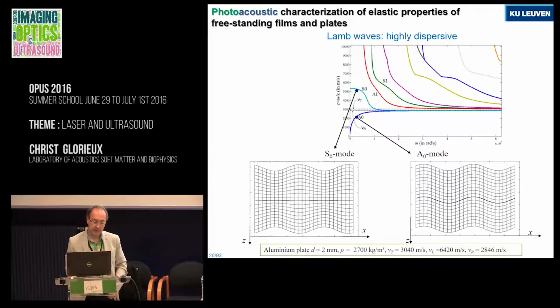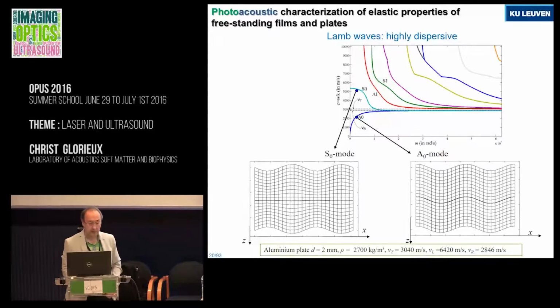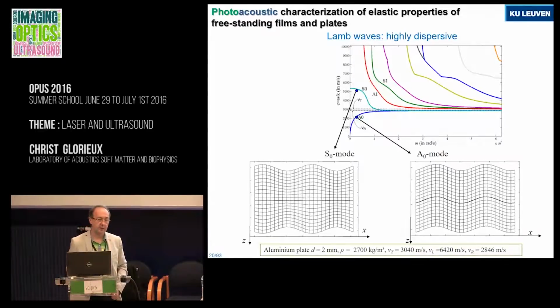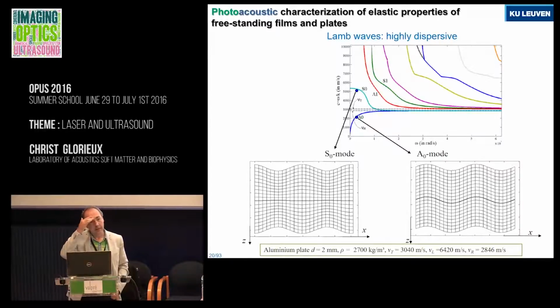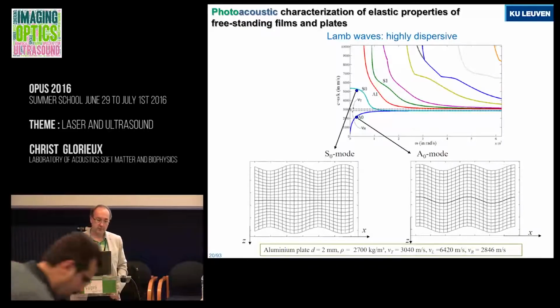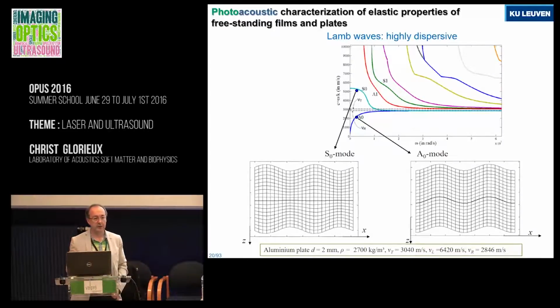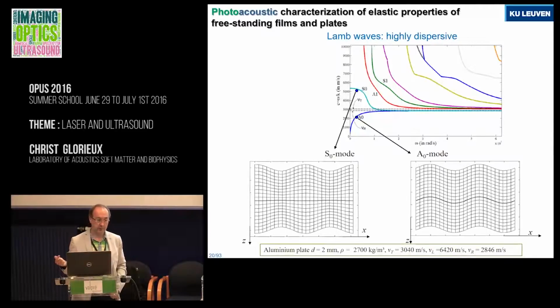So it means that, for example, here at low frequencies, the wave speed is small. As you know, I think the speed of a wave is determined by the modulus. The stiffer the sample is, the less compressive, the faster the waves go, and it is inversely proportional to the density.